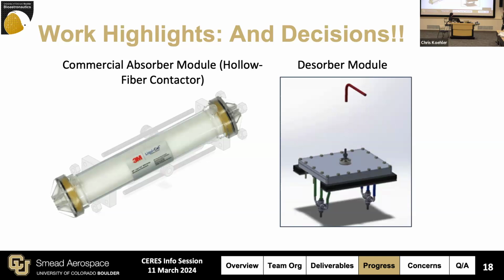And effectively now you can shove liquid through these tubes and air on the outside of the tubes, and the air will permeate into these porous tubes, but the ionic liquid can't get out. And so that makes it a really high surface area contactor and really, really efficient for pulling carbon dioxide out of the atmosphere.